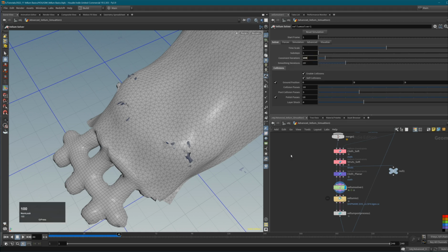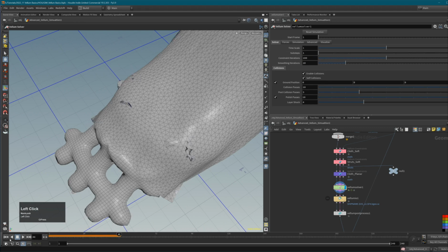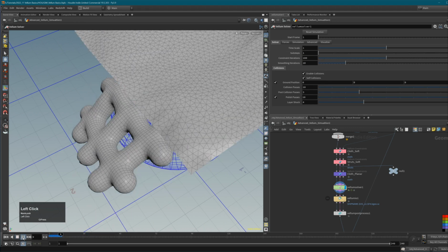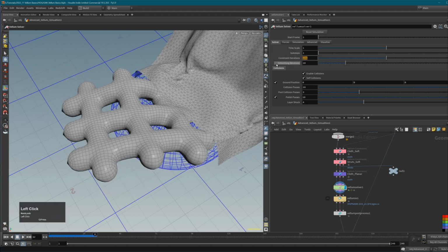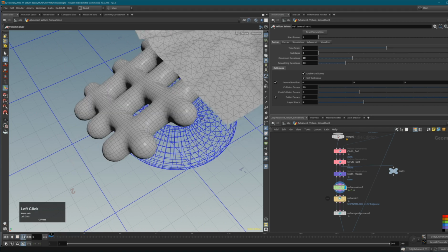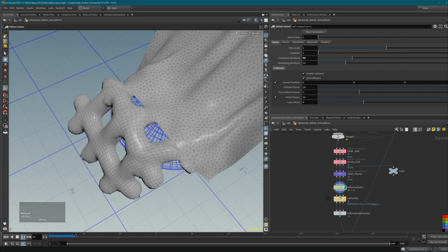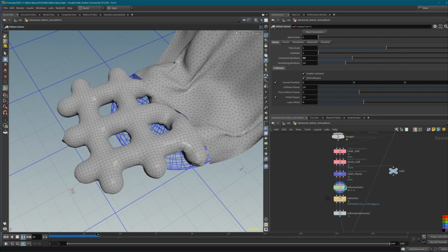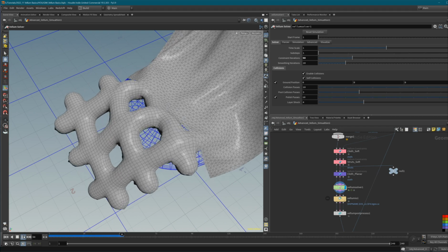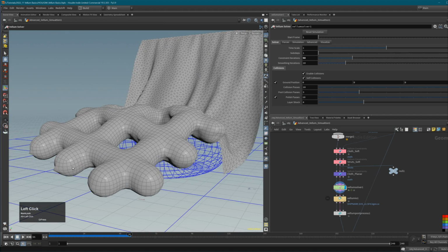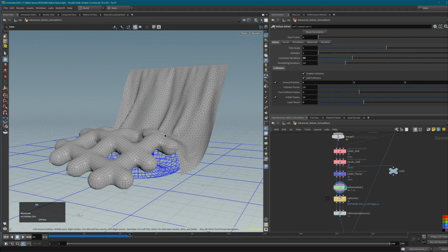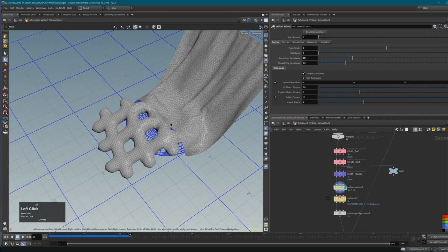You see that we can solve this simulation with 100 constraint iterations. So it works, we get no bad intersections. Let's see whether I can lower it to 50. Let's see where the breaking point is. 50 seems to still work, but of course you see here we get some problems. This is now suddenly popping out. And it just doesn't look that good anymore. So I think we're already at the limit.